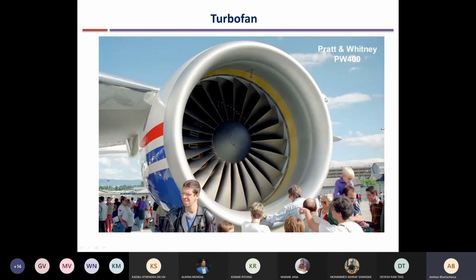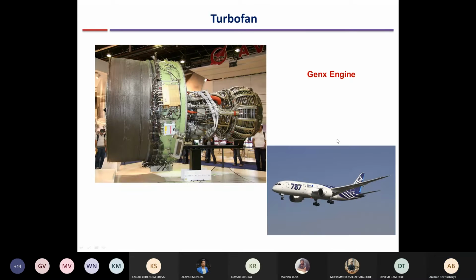Actually, this region in front of the fan, this is a turbofan engine, but this portion that you see in front of the fan is not just arbitrarily designed. This is actually a diffuser with an increasing cross-sectional area. Any of the large aircraft that you board nowadays are turbofan aircraft. So the front section, if you look carefully, you will see the section like this. Then you can see the fan, and inside you will be able to see the other core engine area. But the front section is the diffuser where the air is slowed down.